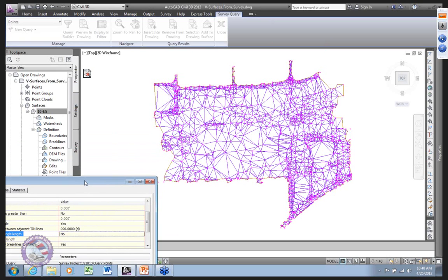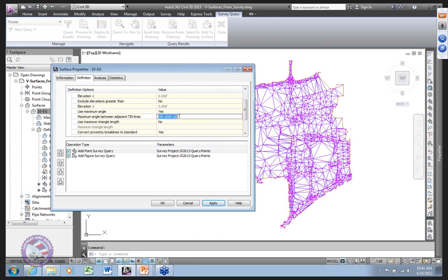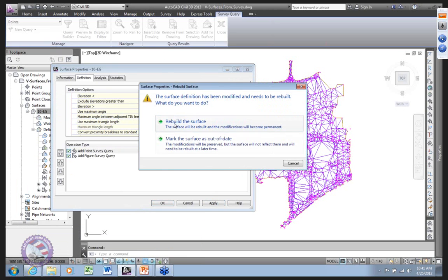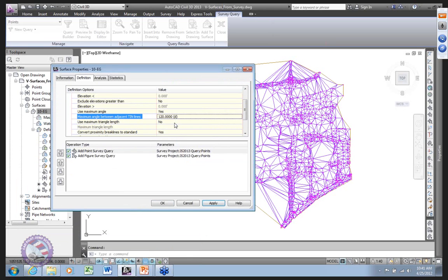And as you can see, we get rid of lots of stuff around the edges. Doesn't cover some of this stuff in here where there's C's, but handles that. Still makes some holes at 90 degrees, so you do have to be careful. Let's go 120 degrees, hit apply, and that will chew less.